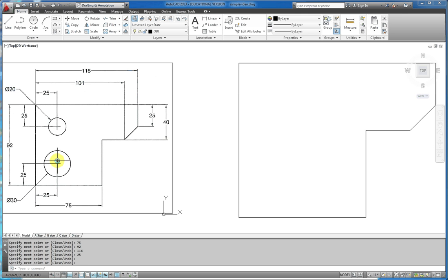So I'm going to use, instead of a regular line, a polyline just because they're a little bit easier to erase. They behave exactly the same way as lines, except it's all tied together as one part. So I pick the polyline tool. I start my line in this corner, and again I'm paying close attention to make sure that I'm using my object snaps. You see the object snap symbol there, the greenish color square.